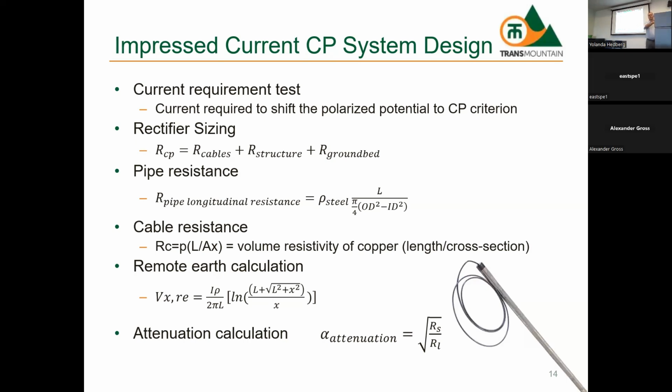This looks simple, but it's actually not, because RS and RL, which is the longitudinal resistance, there's a separate formula to calculate it, and a separate formula to calculate the other resistance values that plug into this. Okay, so that's based on the pipe characteristics, coating type, size of pipe, how far away. You can do this calculation at different lengths to see how far you're going to get.